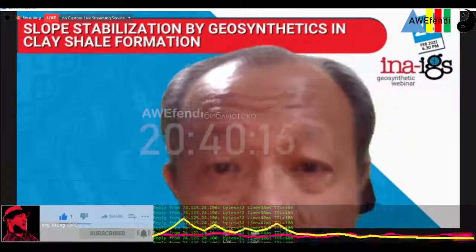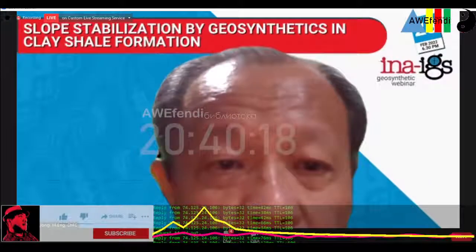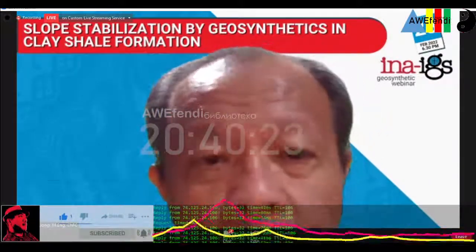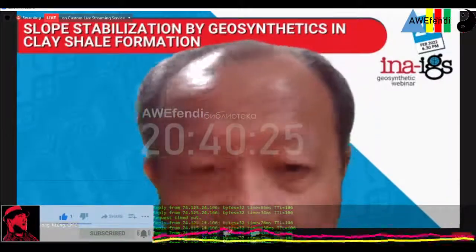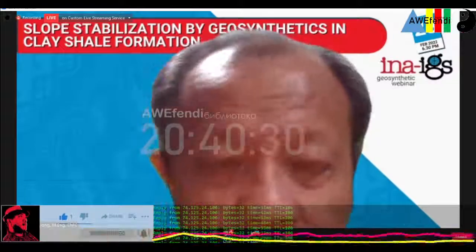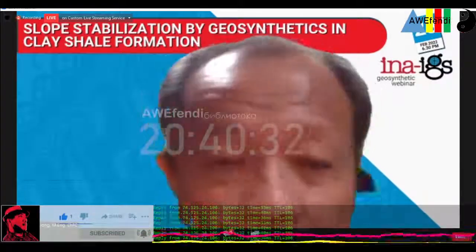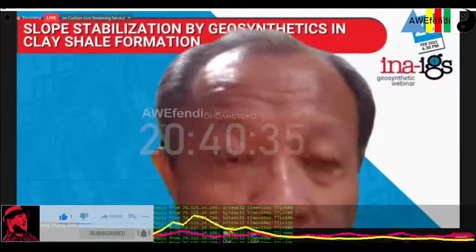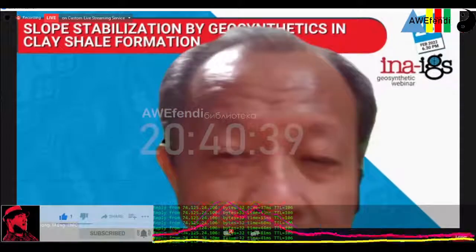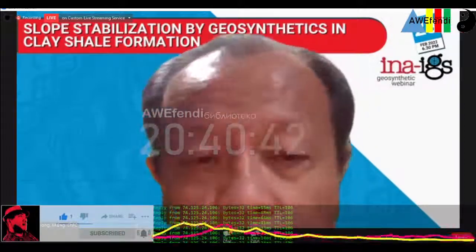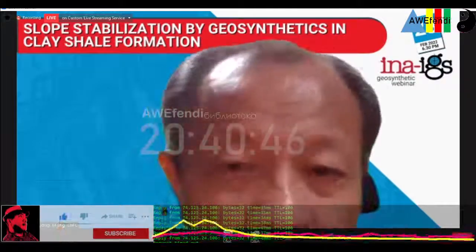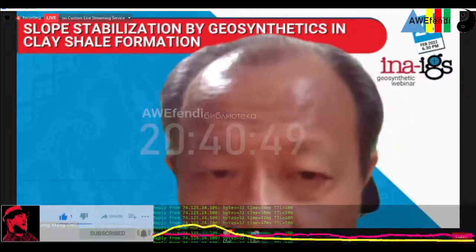Ideally, what test should be conducted on clay shell formation? This question is from Ganesha Putra. The same thing, I think. Everything is the same test. But you have to know that when we first test it, it is covered by thick clay soil underground. When we do the SPT test, you can get very high values, normally above 60. That is why a lot of failures occur only after they excavate and it is exposed to the outside weather.